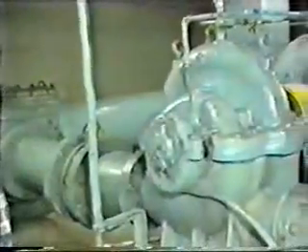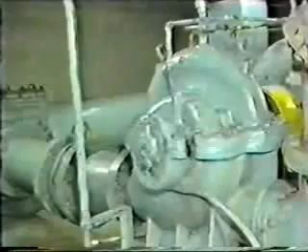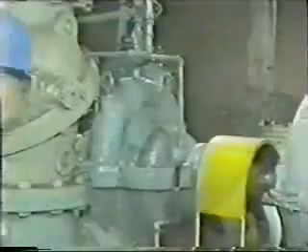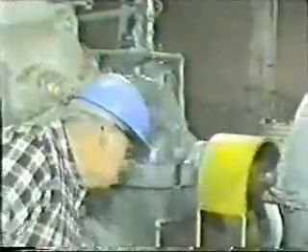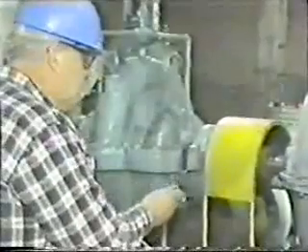If the temperature did exceed operating limits specified by the manufacturer or facility, you'd have to shut the pump down to protect it from damage. Of course, it's helpful to be able to observe the equipment in operation, but it's not always possible since operating equipment, when it's malfunctioning, could damage the equipment. Gene goes on to check the temperature reading on the other pump bearing and on the two motor bearings.